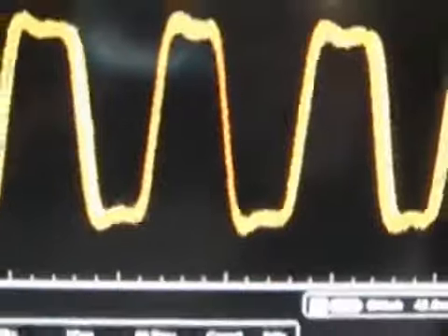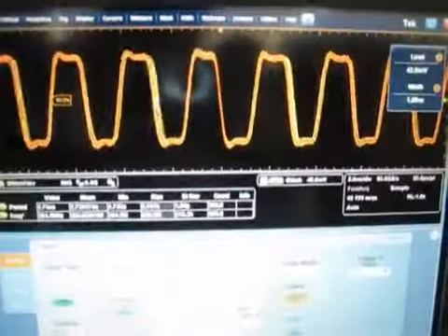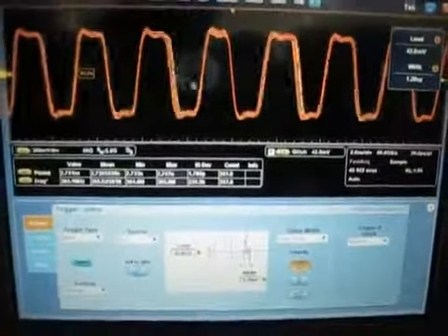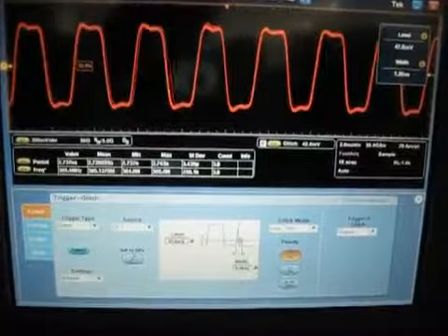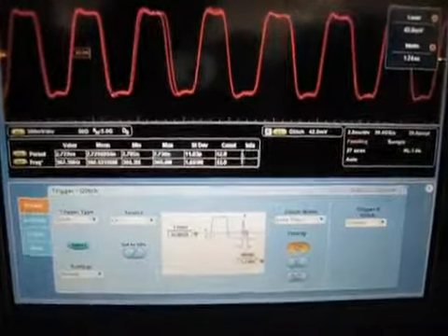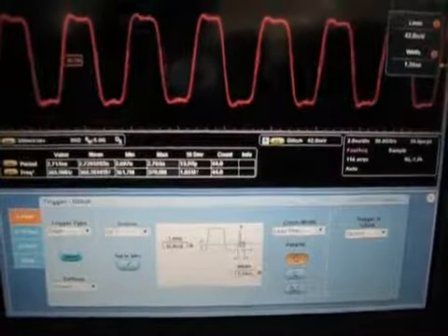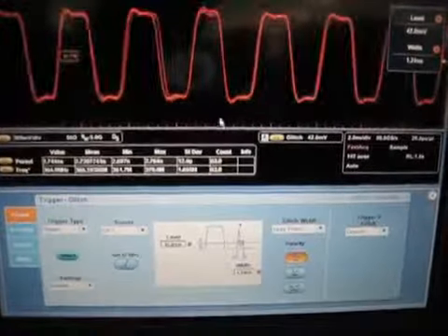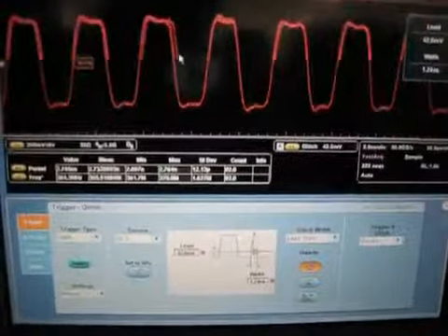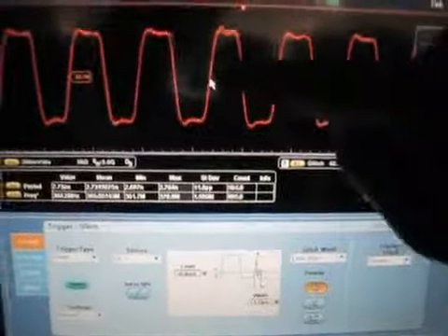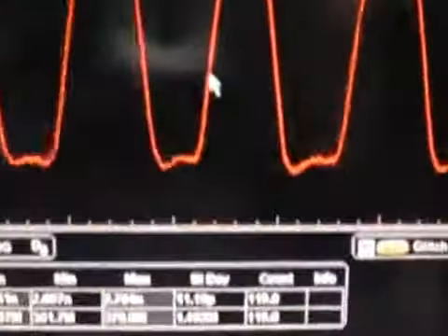And also there's some timing distortion jitter on the bus. When we continue to go down, finally we see, if we set the pulse width to like 1.24 nanoseconds and move close to here, there's some interference.